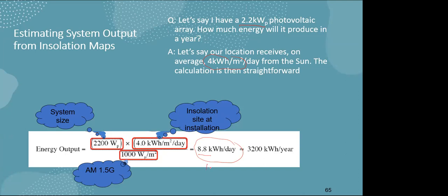Here that is 10 kilowatt hours. Then the panel capacity needs to be calculated. The insolation at the site, Colombo, is around 5 kilowatt hours per square meter per day. That's a rough calculation you can follow to estimate how much solar panel you may require to generate the required amount of kilowatt hours per day.